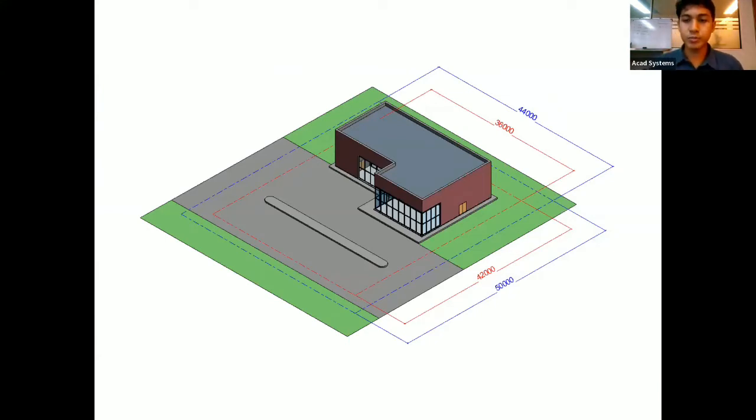So for today's process, before we jump into Revit, this is the overview. We have a simple building like this, and I want to create a roof on top of it. Here I just prepared a roof line for guidance. This red roof line is smaller and the blue line is bigger. I'll show you how I change the dimension, and the pattern will follow through accordingly.